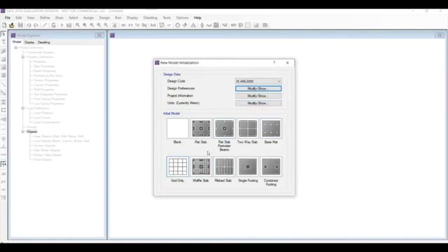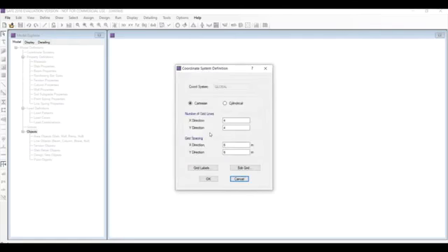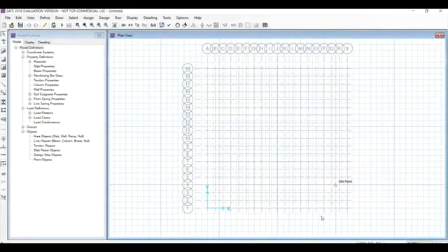And now go for grid only, as we don't have a mat foundation prescribed format, as we have only base mat, but we just go for a grid only system so that we can have our own dimensions and our own columns. And for an 18 meter mat foundation, we need at least 19 grid lines, if we take each 1 meter as one interval spacing of the grid line. So take x direction 1 meter spacing and y direction 1 meter spacing and click OK. Now we have the grid lines of our mat foundation.